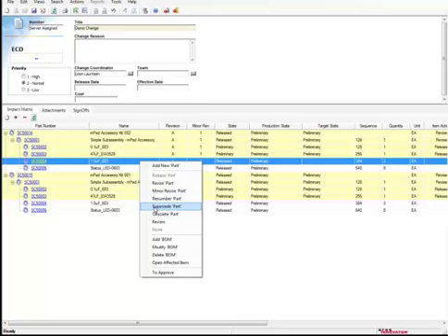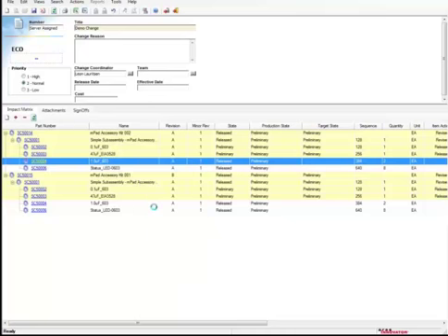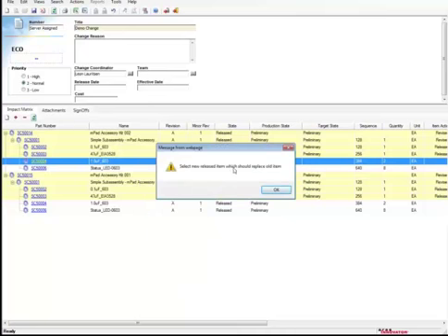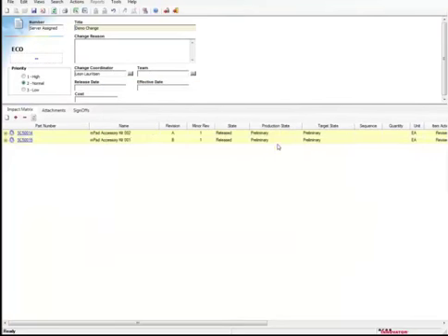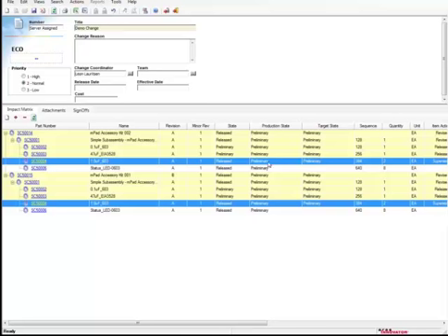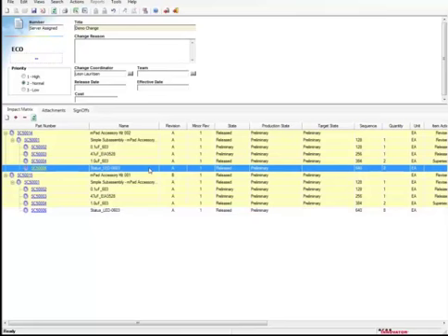As you can see, there are many different options, and we'll talk a bit more about them in just a moment. By clicking on the supersede button, it prompts me to state that I need to find a different released item, and then it opens up the search element. I'll then search for a replacement component, find it, and state OK. So now, as you can see again in both places, it has defined what is happening in this change.